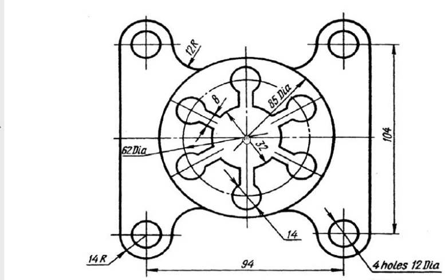After fixing the origin at the center, we'll make 3 concentric circles. The first circle will be of dia 32, the second circle of dia 62, and the third circle of dia 85. After making the 3 concentric circles, we'll change the solid line to a center line for the center circle. Then we'll make a smaller circle of dia 14, and then we'll draw these 2 lines.